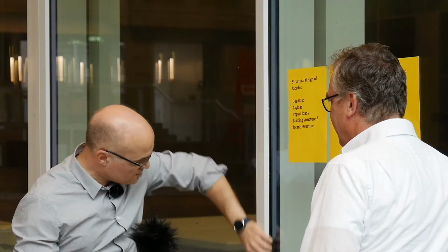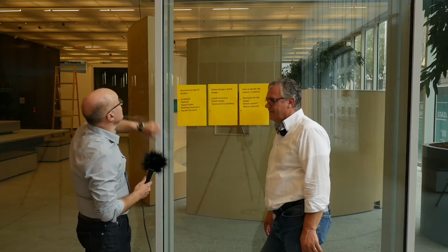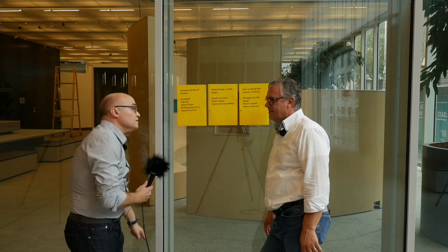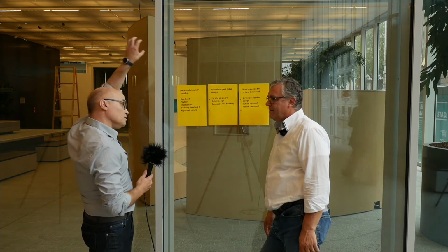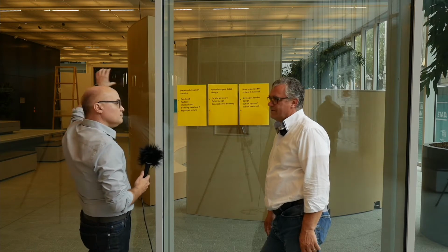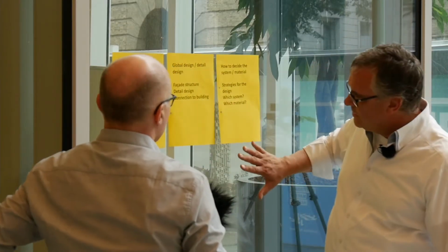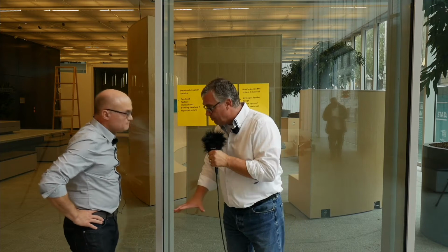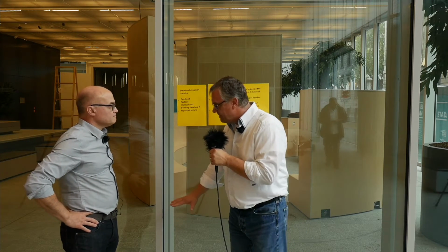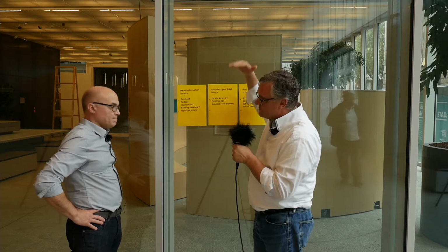So then this mullion in its own right must transfer the load to where it is connected to the structure. In this case here it's in the ground, but as you go further up it might be connected to a beam or edge of slab in your floor. Okay, so then the loads from the facade are transported down and brought into the main structure. Yes. But what happens if I have more than just one floor? What about the second and the third floor?